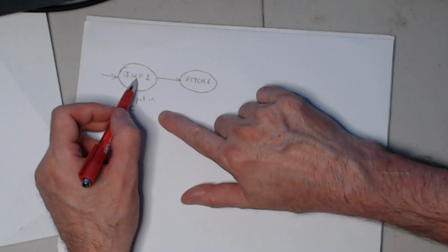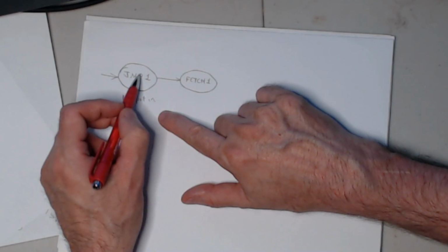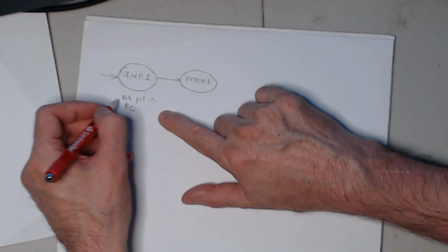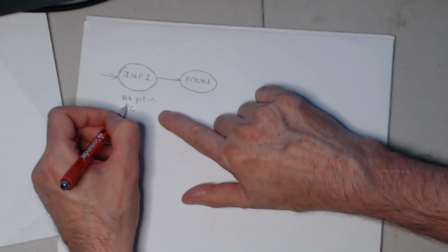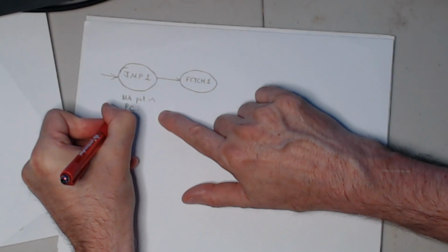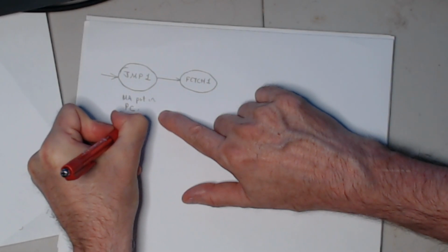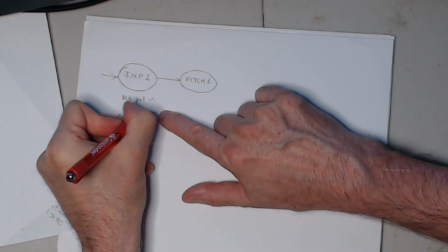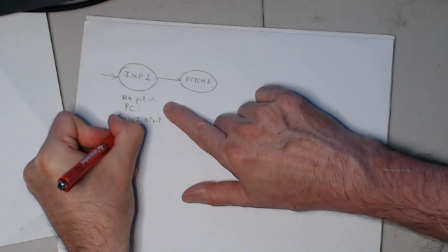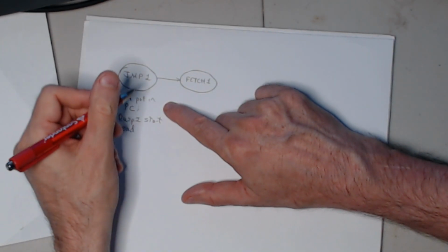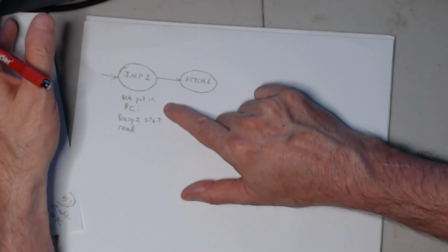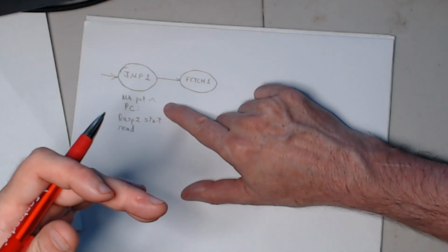But what we can do is, see, this jump cycle isn't doing anything with the Raspberry Pi, and we have the address of the next instruction here already, so we can simply tell the Raspberry Pi, hey, start reading that location. Read. Because remember how the Raspberry Pi memory read goes. You take one cycle to send the address you want to it, and then the next cycle you read the data back.